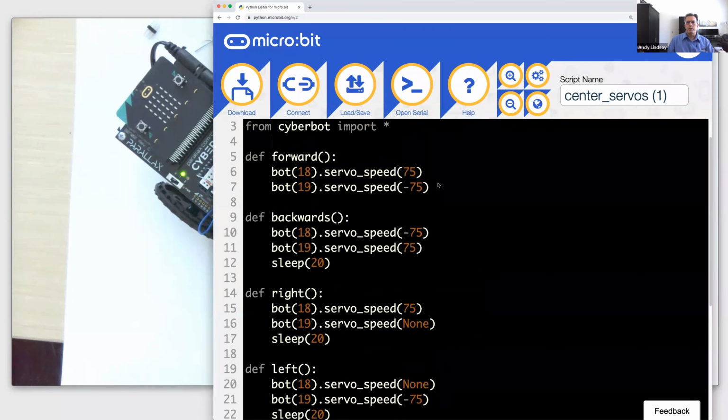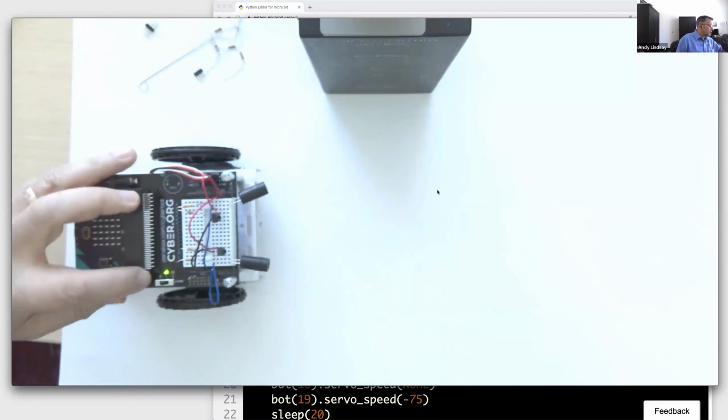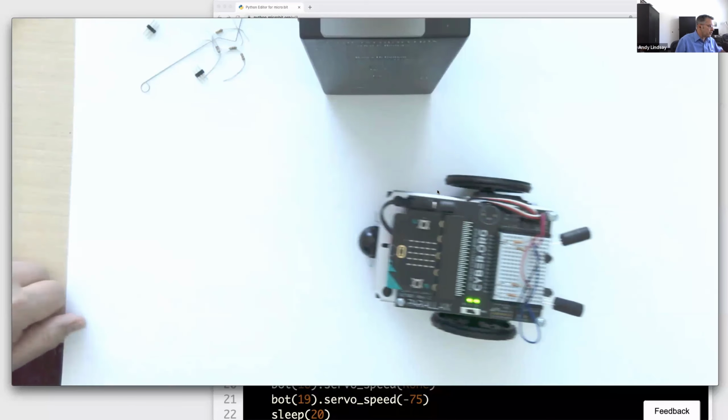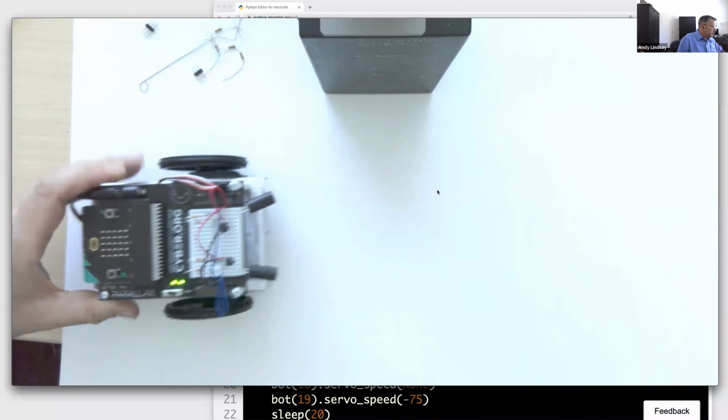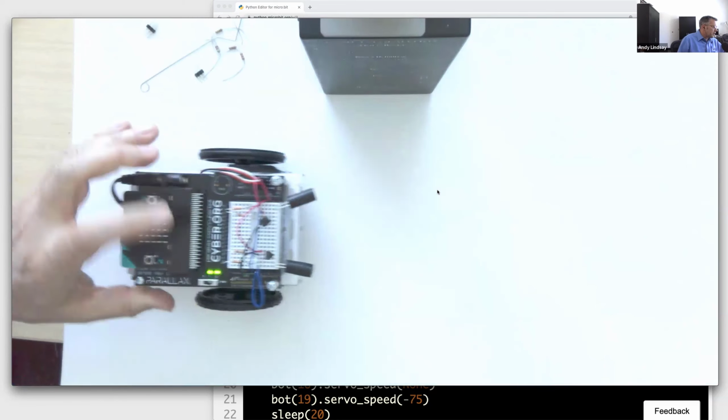If you have one wheel that turns a little faster than the other, it's usually best to slow down the faster wheel. So I'll switch and let's test and see which direction mine goes. Actually, mine's going nice and straight. One thing you can do is just use 200s instead of 75s, and that'll straighten it out.